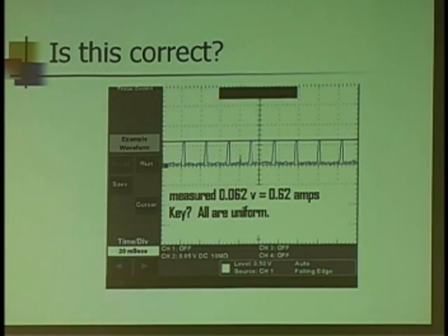Here's another great tool, use of the scope. Monitoring the current for all of them at one time. You can use this not only for injectors, what about the Nissans with the coil issues? Was it the Maxima V6? What if you monitor the current and one of the coils starts acting up? Do you think you're going to see it in that pattern? Sure you will.